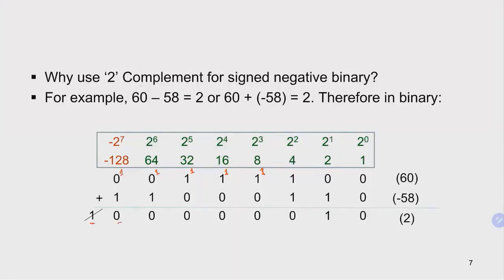So we start off with 8 bits, and the sum of this ends up with a 9th bit. We will discuss this 9th bit later. And you can see that the 8 bits now become 0 at the sign bit. So this indicates that this is a positive number. This shows it is positive, and this shows this is negative.